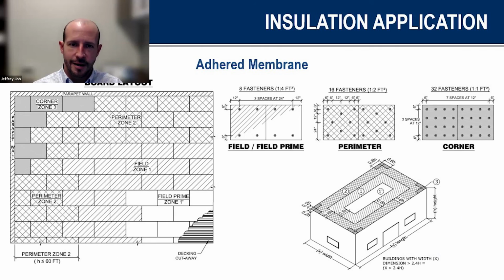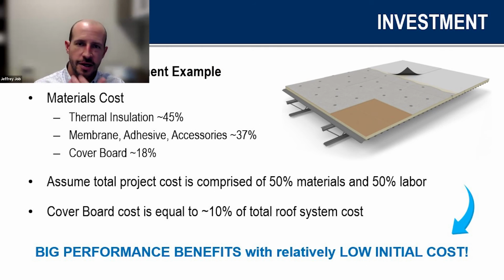Yeah, I would say I like to go back to the return on investment. Using a coverboard is going to give you significant protection of your insulation package, and a very good, robust substrate to adhere your membrane to. In the grand scheme of things, it's probably a 10% cost component when you factor in labor and everything else, whereas those other two components are 40, 50%. Those are huge cost drivers, so mixing in a coverboard is really going to allow you to protect those major components.